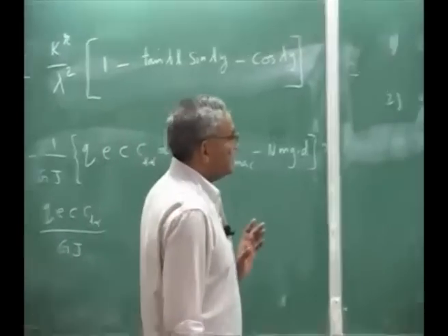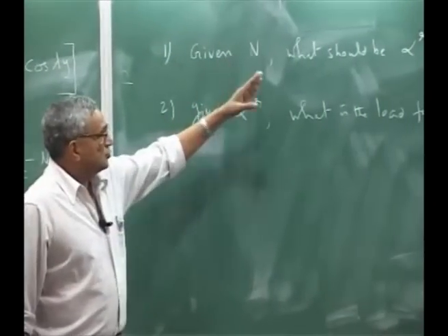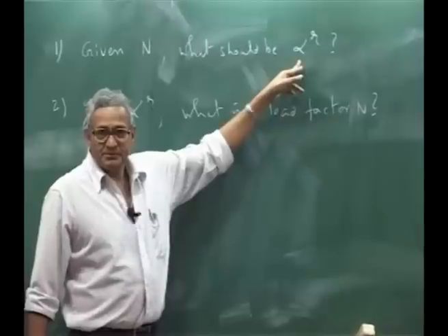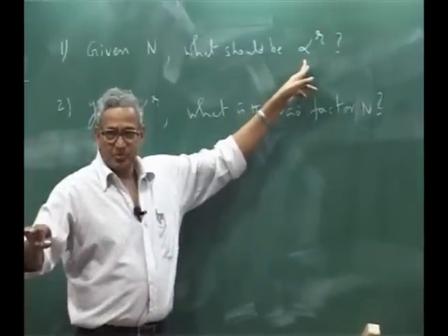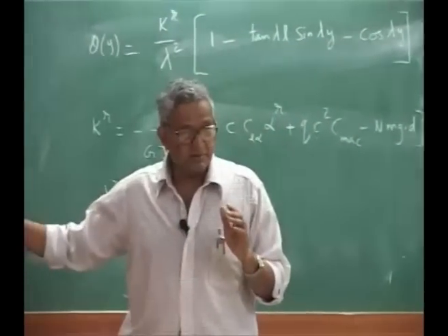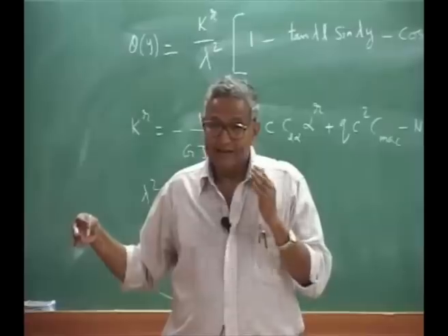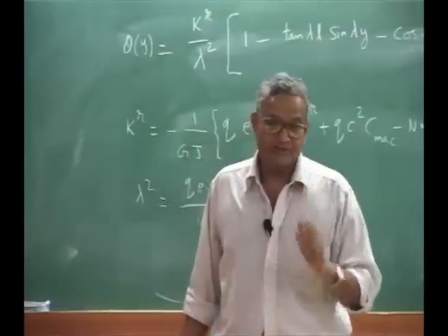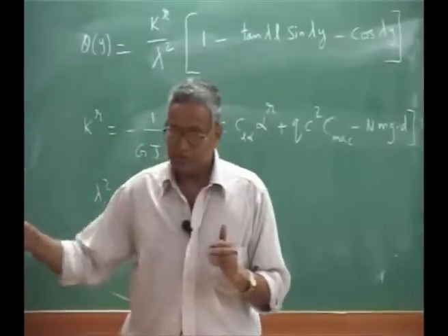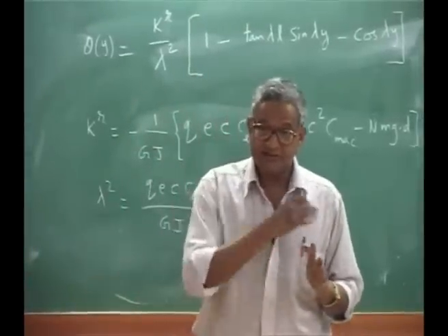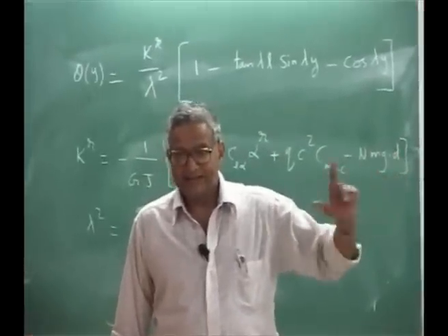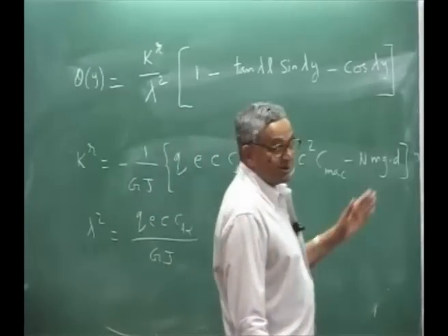Why we need to do that is, if you set any angle as a rigid alpha r, because of the flexibility, your load distribution is going to be different. Because of the wing twist, the lift distribution will be different from when the wing is not elastically twisting. If the load distribution changes, that means your sectional bending moment, shear, everything will change. If that changes, your structural design will change. That is the reason you need to do aeroelastic calculation for structural analysis.